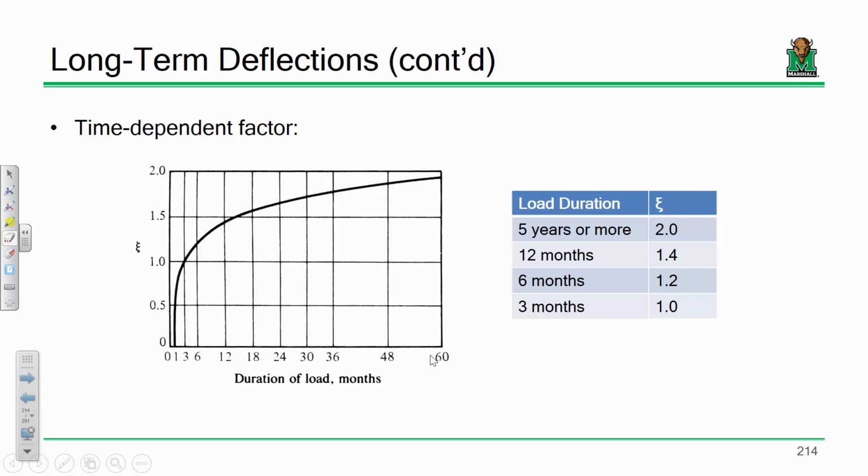Let me supplement that answer a little bit. That comes again from engineering judgment. For instance, if you're talking about a classroom scenario, if we agree that maybe 20% of that load is sustained, it's also a function of whether that load is going to be there all the time forever, or only for a certain period of time.